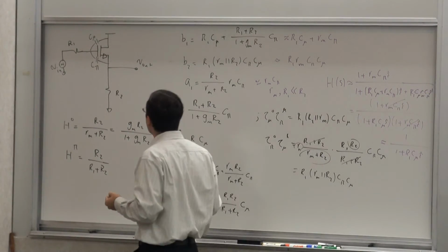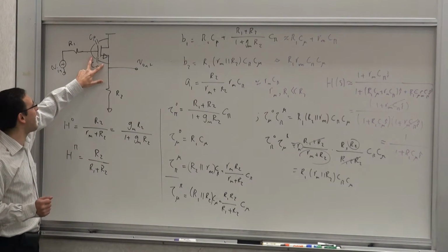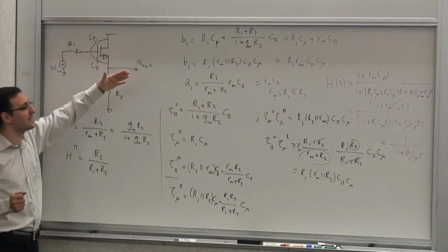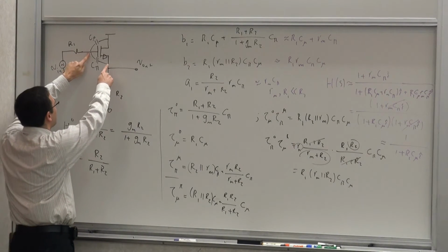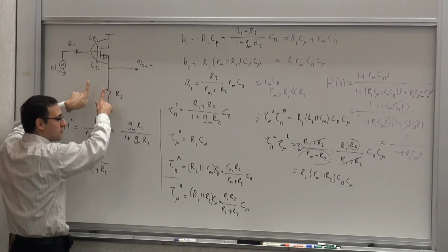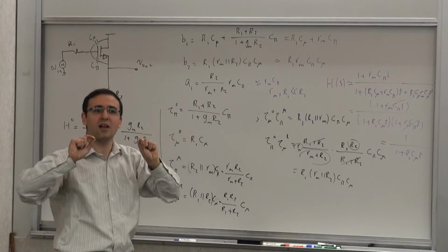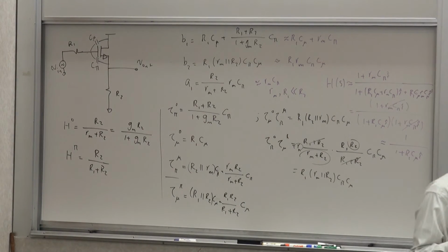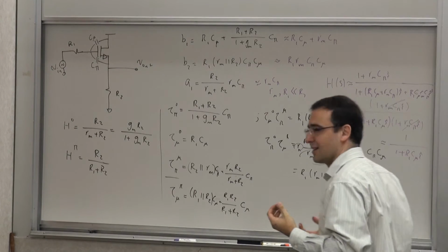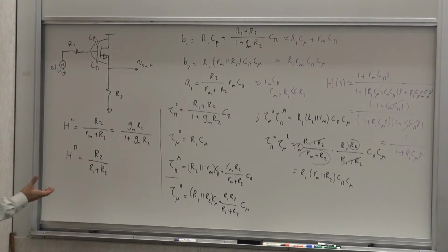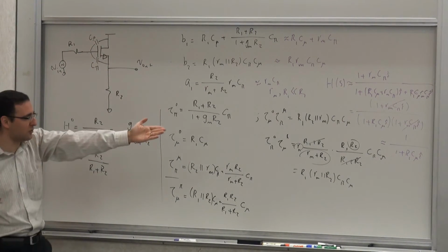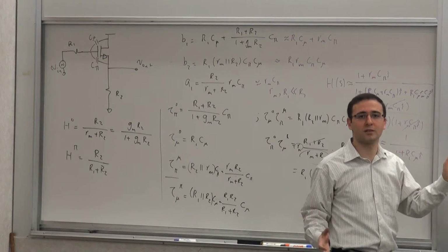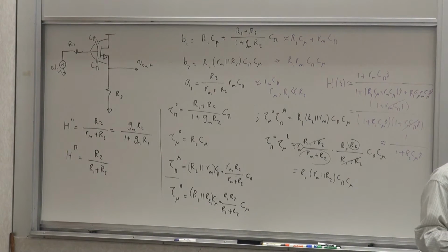And this also goes back to our way of thinking about the Miller effect. Because the effect of this capacitor, if the gain of this stage is large, which is what it means when you write R2 is greater than Rm, makes the gain close to what, right? So the gain from here to there is close to unity. So this side goes up, that side goes up too. They go up and down. So you see basically a lot less swing across the capacitor. So the effect of that capacitor is very attenuated. It's less significant. And C mu becomes more dominant. Okay, any questions?